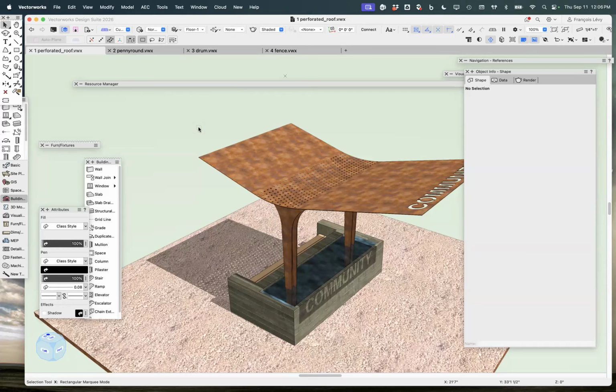But in the Y direction, I also have a 3-inch offset, and I've given it a shift factor of 0.5. That's what's giving me that staggered rowing. If I made the shift factor 1, then they all line up. I could make it 1/3, and then they would be sort of a hexagonal pattern.